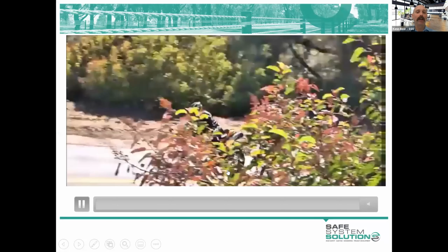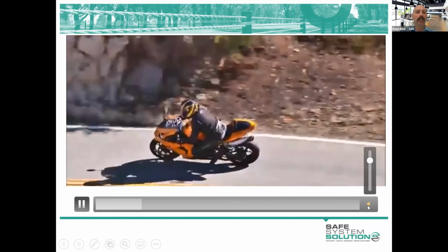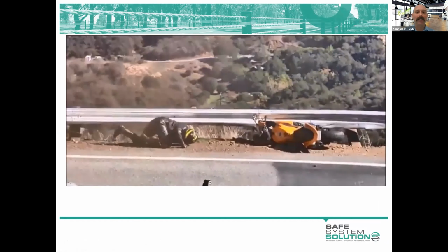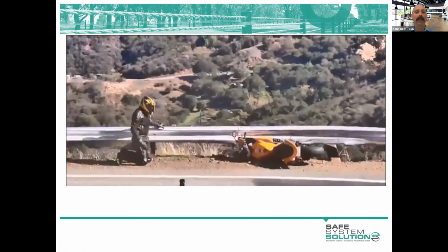And the other is where the rider is off the bike and sliding and strikes the base of the barrier system. And that's about half the time that they're already off and sliding and hit a post. Here's another motorcycle dummy in a crash test scenario, sliding along somewhere near the bike, but they will pretty much always separate, and the rider pretty much always finds a post and strikes the post. And you see there the post, even though that's a flexible system, the post pretty much doesn't budge with the weight of a motorcyclist.